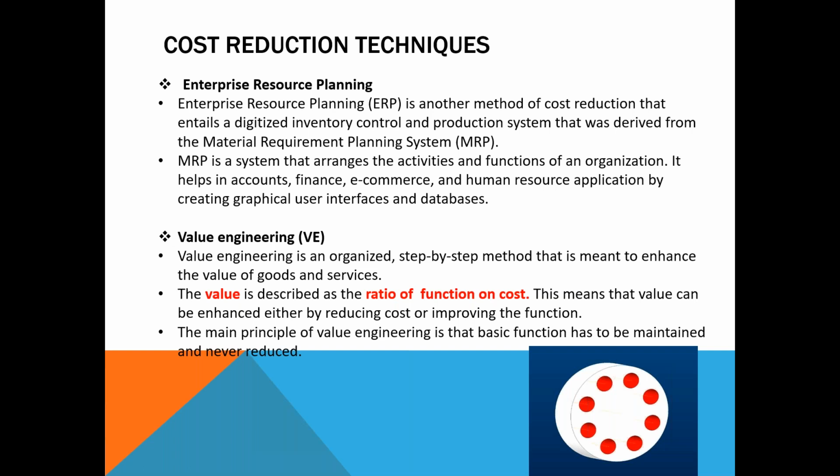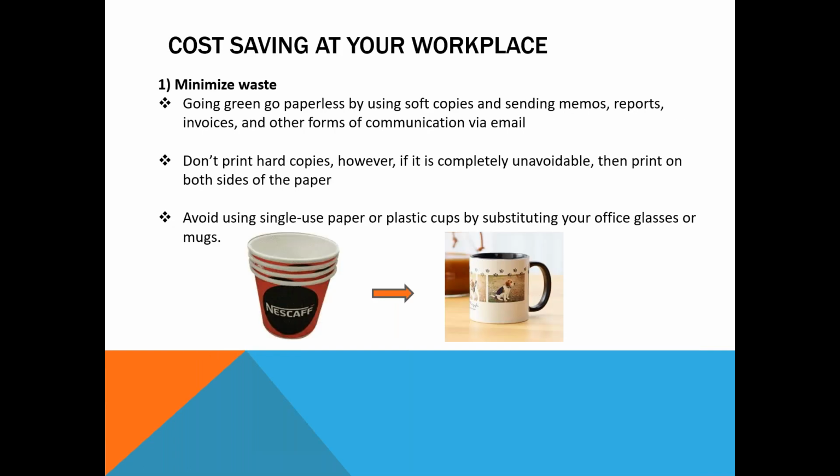So to minimize this, the sulfur was reduced from 0.02 to 0.014, and this gave good machinability, and the forgings were without any crack. Mind well, this took a long time, it was a step-by-step organized method, and it was very difficult to convince the steel mill. As of today also, they are in a monopoly business. So this is nothing but value engineering.